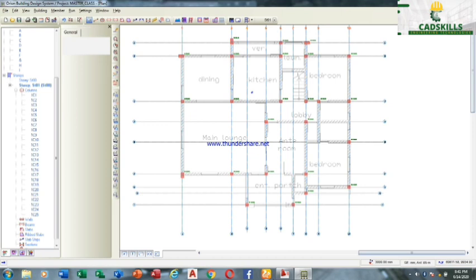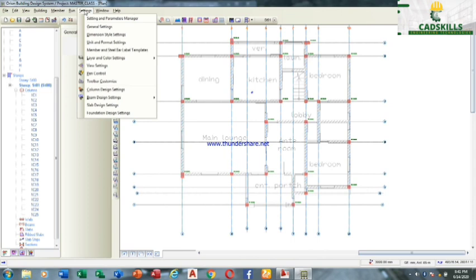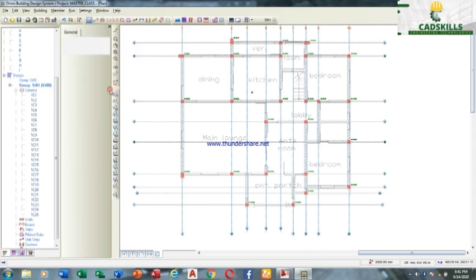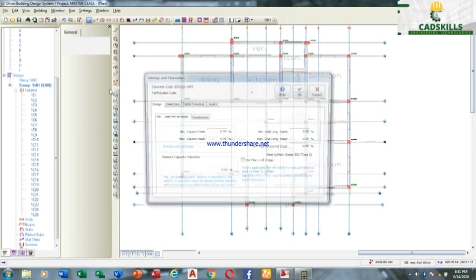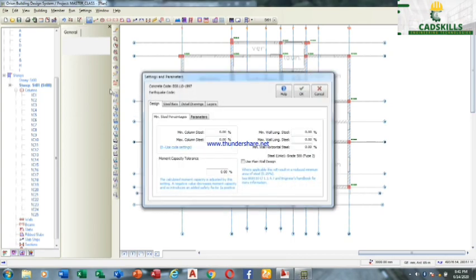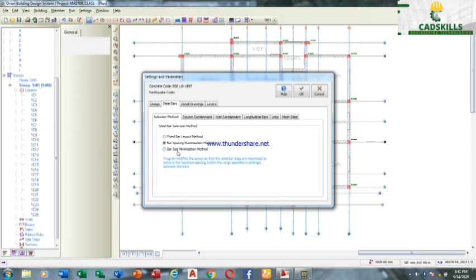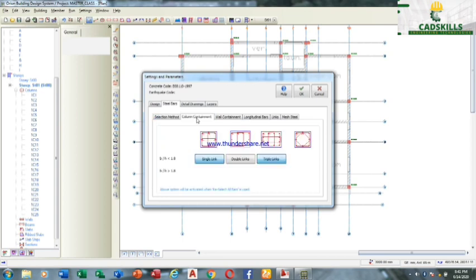Is that okay? Now, first and foremost, go to settings, set all your beams, set all these things. Column, you have put columns already, just click on column, set it, take time. This is design. Come to steel bars, bar spacing maximization method. Yes, leave it like that. Take time to go through it. Let all these things be there.